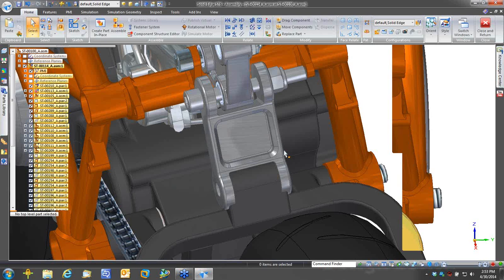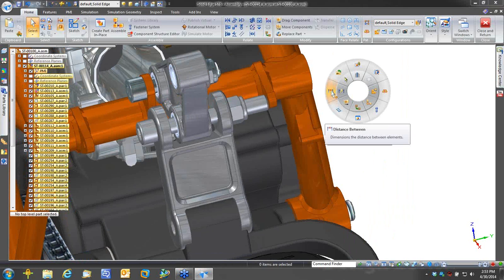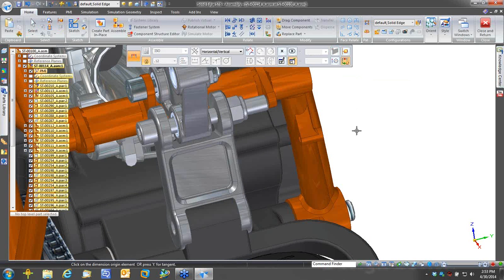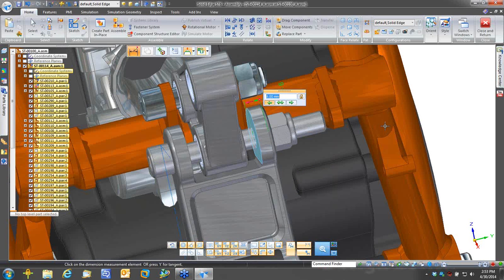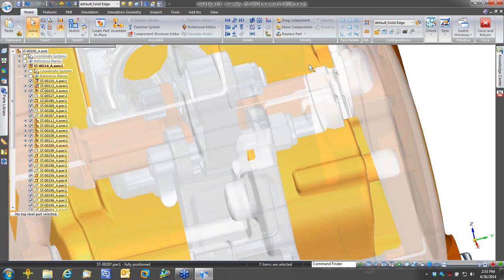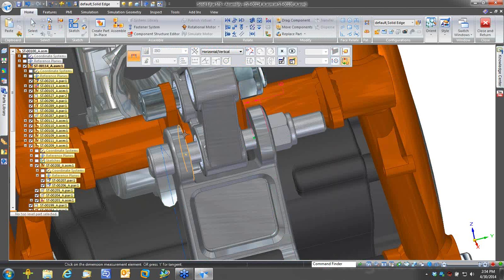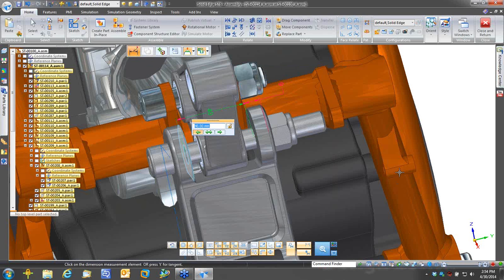So what I want to draw your attention to is right here at the assembly level, I can make a change to my mounting arm. And again, I'll go to my dimensioning tools. And what I can do is I can say, let's add some additional dimensions. Maybe we didn't have these initially. So let's place a dimension maybe on that ear. And we want to maintain that dimension. But also, let's place a dimension between these 2 locations. And you'll see that that's 40. And that's where the interference is coming from, is that's not wide enough.